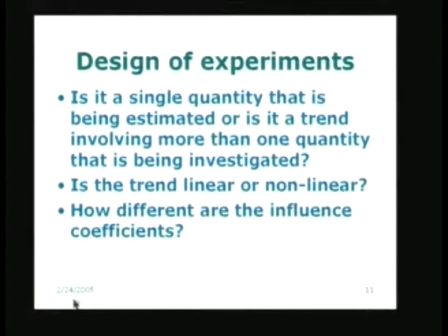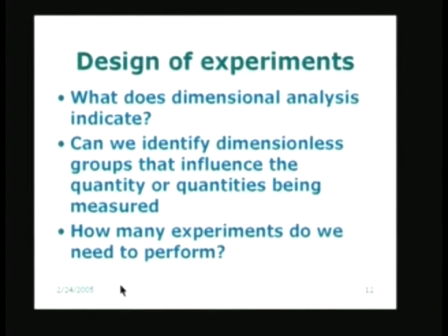So we would like to make the experiment and find out which factor has the higher influence. There may also be an interaction between these factors. If the speed of the machine is very high and the depth of cut is very small, or the depth of cut is very high and the speed of the machine is low, it may lead to different types of interaction. So the two factors may even interact, and the outcome of the experiment may depend on both of them simultaneously. Therefore, to answer all these questions, we would like to do the following.